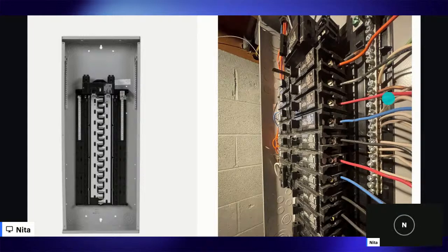Okay? Our lugs. Lugs are basically these screws. They're the mechanical connectors where our wires attach to the bus bars. So here we have a lug here, here. All of these are lugs, where wire is connected to the bus bars or the terminals. Basically, they're heavy duty screws and they clamp down on the wires.